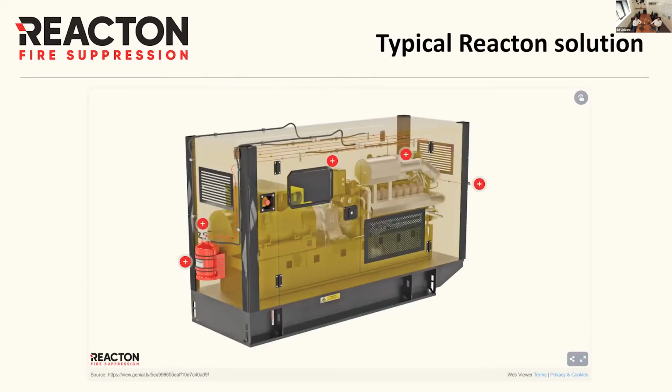And I think it's probably worth going through, because really it's probably worth saying that where we have an electrical only risk, main risk, that's where we're looking at clean agent. And where we're looking at the dry chemical and wet chemical systems is when we have larger diesel engine generators as being the primary driven source. That's the comparison that we're doing. Right, so let's walk through this.